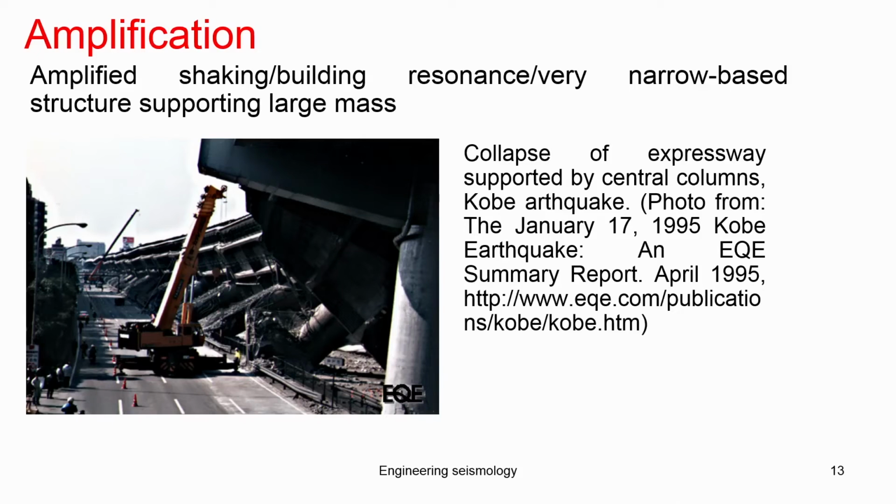That causes a wave change that we discussed as amplification. That amplification produces an additional force on the structure that causes a collapse. Here the structure may have been designed, but because of the amplification effect, the force you considered is insufficient. So that causes an amplification-based hazard.